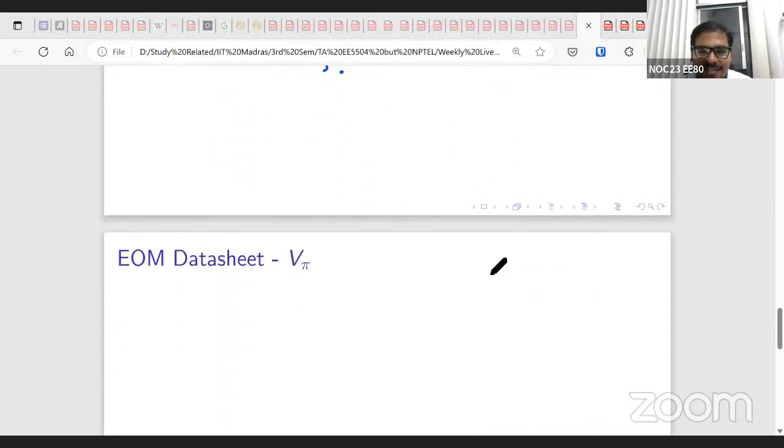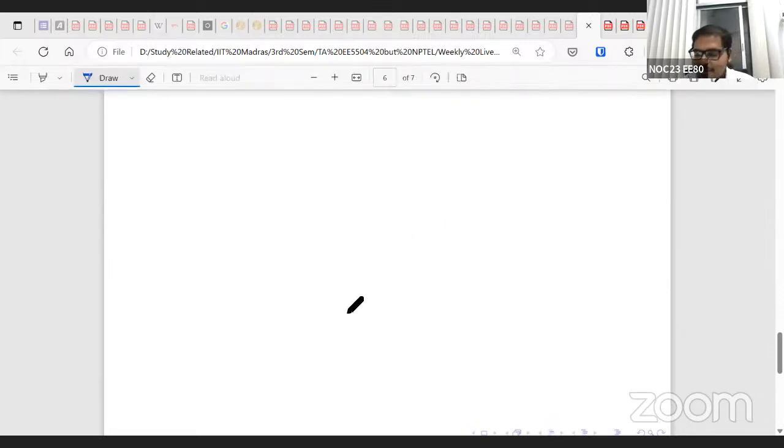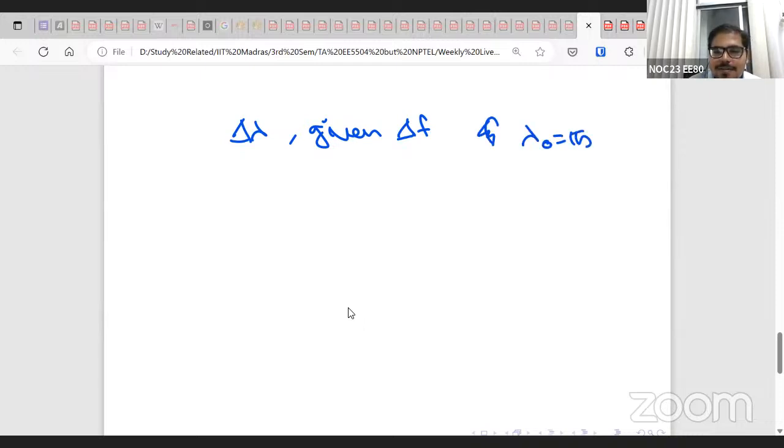And the other thing that Namamita asked, I think, but I didn't answer because I kept forgetting. There were multiple steps in a question, but the one part you'll be encountering frequently is asking what is the change in wavelength given the change in frequency. Here we always assume that the central wavelength is 1550 nanometer, and you use this relation.